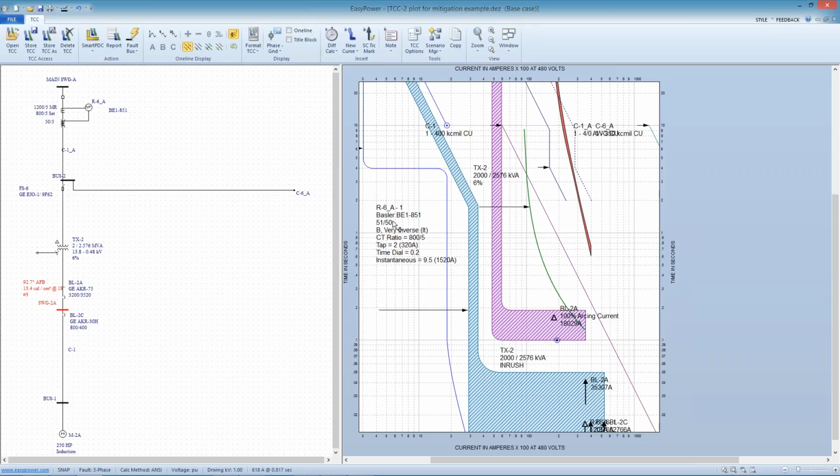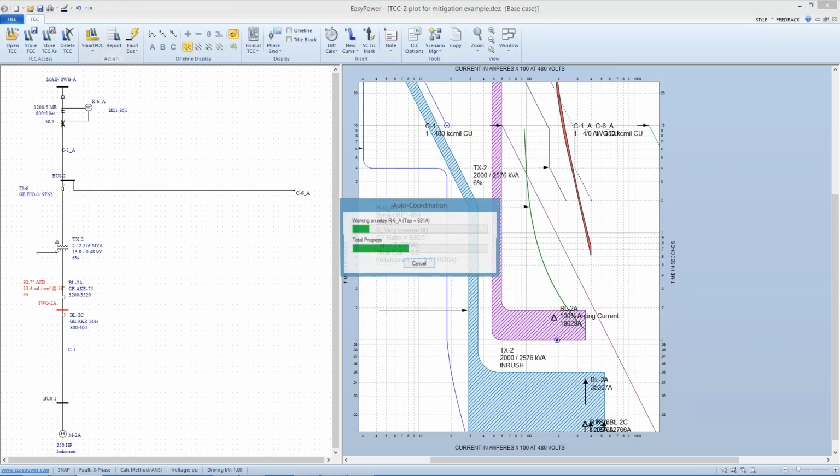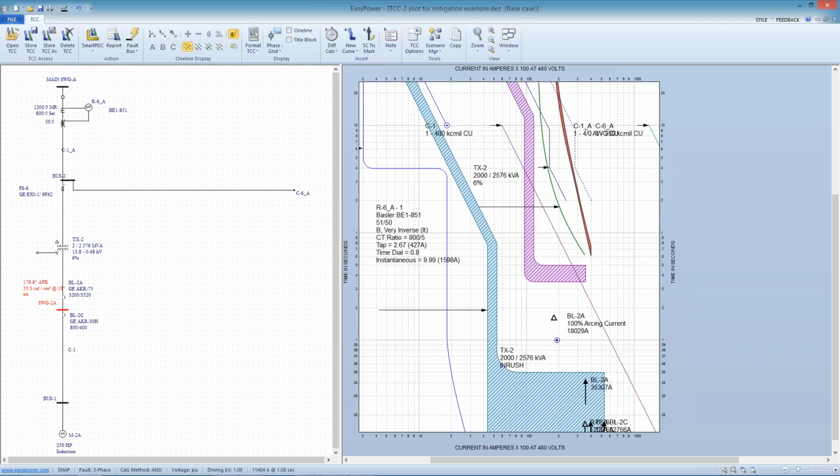Now, I'm as guilty as anybody else. Once I'm in this kind of a mode, it's nice to know what Smart PDC would recommend for these settings, and by invoking Smart PDC, the tool comes back with these recommendations, which again took my incident energy up, but it did readjust the breaker, and so now I can see that I have clearance, and at that point I think I really want a power systems engineer to look at the coordination that we're trying to achieve for this downstream.